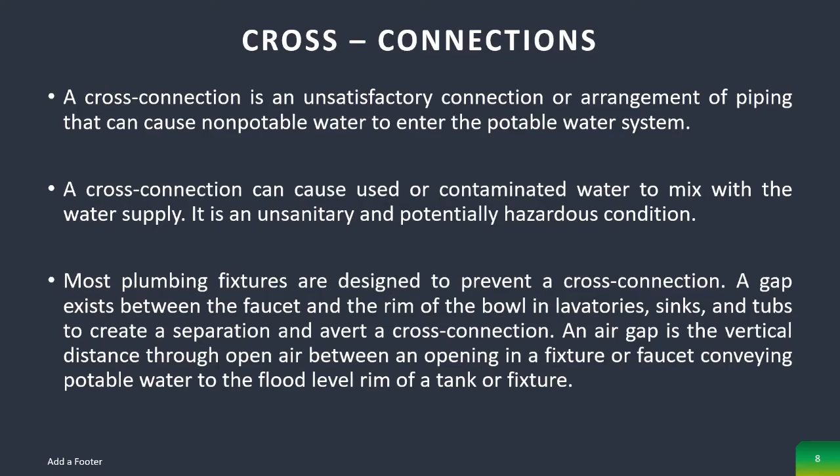Number 3 is the cross connections. A cross connection is an unsatisfactory connection or arrangement of piping that can cause non-potable water to enter the potable water system. So this is a vital concern because it can cause danger to one's health. Once yung non-potable water is mainom mo, di ba? Pwede kang magkasakit. A cross connection can cause used or contaminated water to mix with the water supply. It is an unsanitary and potentially hazardous condition.